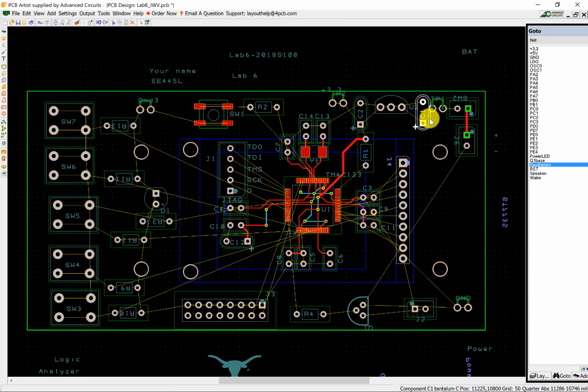And it'll be prettier. It's probably better to move stuff around before you start tracing. Okay, so again, I want the top. If you can read the thing on the bottom, it'll tell me it's a +5 net. On top, copper 20. That's what I want. So I'm just going to connect all of these 5 volts together.